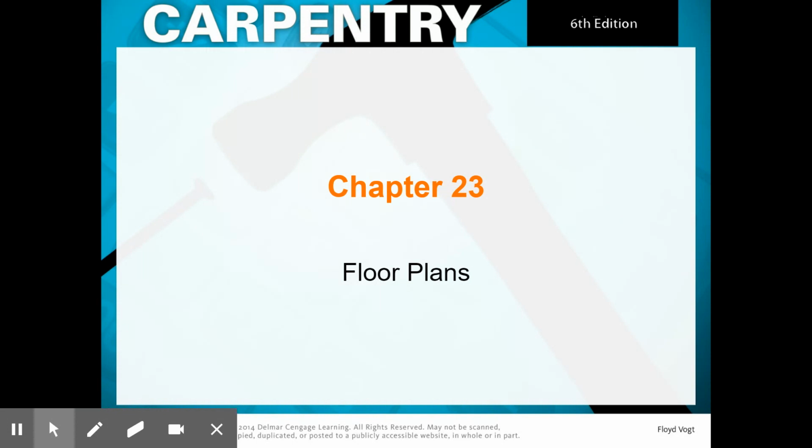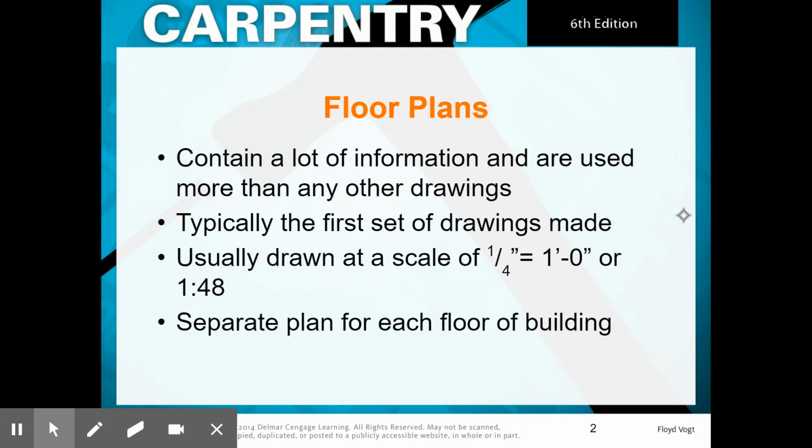Today we're going over chapter 23, floor plans. So in the previous video we talked about floor plans, but in this one we're going to go into a little bit more detail. Floor plans contain a lot of information and are used more than any other drawings as far as blueprints go. They're typically the first set of drawings made, and they're usually drawn at a scale of 1/4 inch equals 1 foot or 1/48.